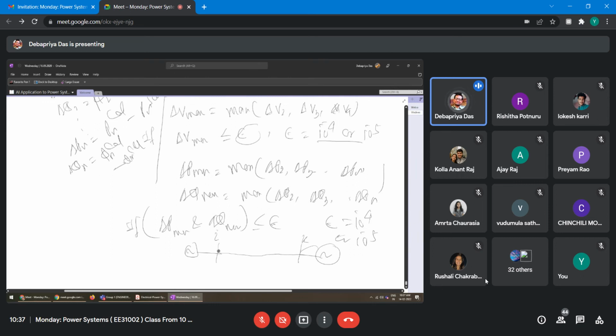Suppose at this point power flow is PIK, because I to K, but at this point, when it is entering along this line, power loss will be there. The same will be true for reactive power also. At this point it will be PIK minus the loss. Here it will be PIK minus PIK loss, right? Because loss has to be subtracted, right?